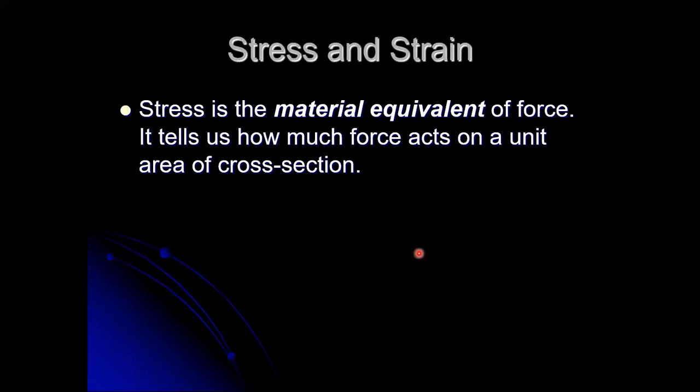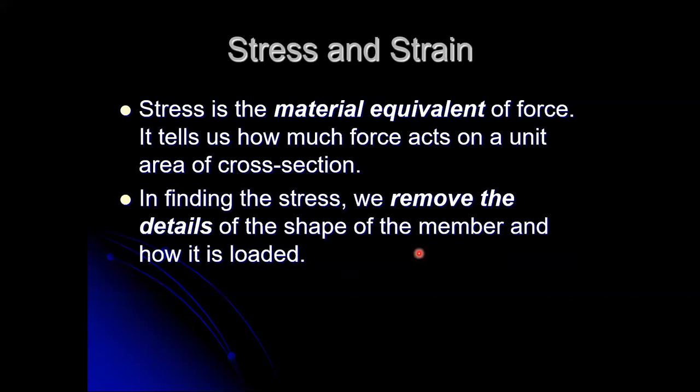And essentially, we consider it to be the material's, or the internal, equivalent of force. It is generated when a force is applied externally. Essentially, it's the material's response to an external force. The internal response to an external force is stress. So it's how much force acts on a unit area. And when we find the stress, something kind of important happens. We actually lose the details of the shape of the member.